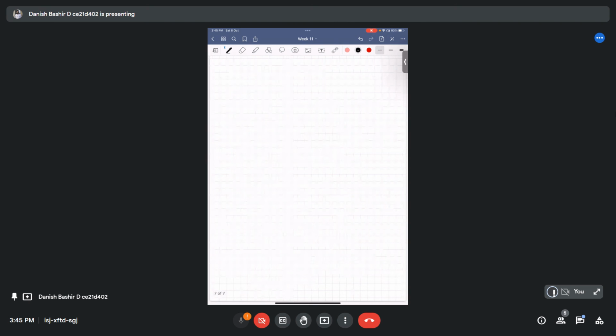So SV required is this one. Okay. Now we have to check the minimum spacing requirements from the code. I told you it should be above the minimum and below the maximum spacing requirements. So the code says that SV should be less than or equal to x1 by 4 or y1 by 4 or 250 mm. Hope you all remember the definitions of x1 and y1.